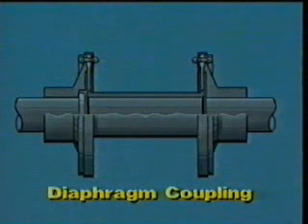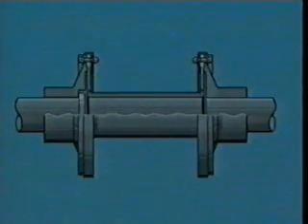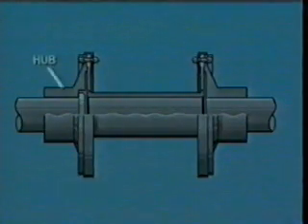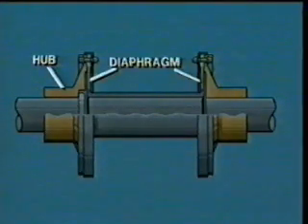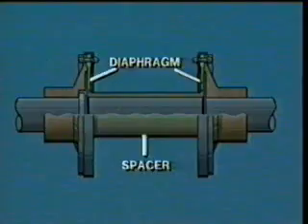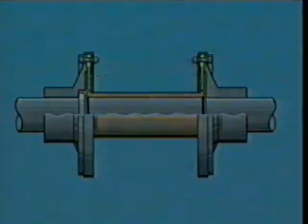The flexible diaphragm coupling is commonly used with turbine-driven compressors, where distortion due to heat is substantial. The flexible diaphragm coupling transmits power from the driver to the compressor using a solid, rigid hub on each unit. A flexible metal diaphragm is bolted to the outer rim of each hub, and a spacer connects the two diaphragms. All misalignment is handled by the elastic flexing of these thin web diaphragms, and there is no rubbing movement of any parts of the coupling, and no lubrication is required.